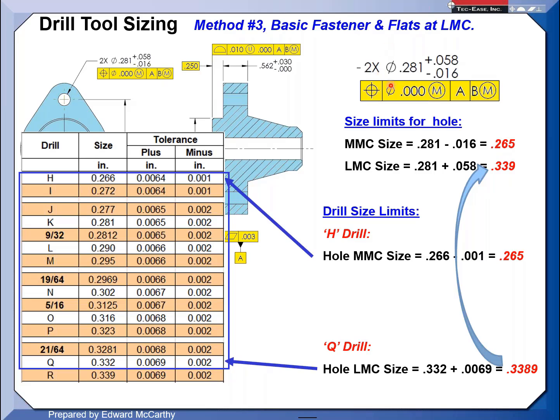And the standard does give you a variety of different options here that you could do in what we call an equal bilateral, where the nominal value is the mean, or you can do a unilateral. I could have driven this all the way down to the lower limit, make this 0, and then give all the plus up here, as long as they all give me this answer here.